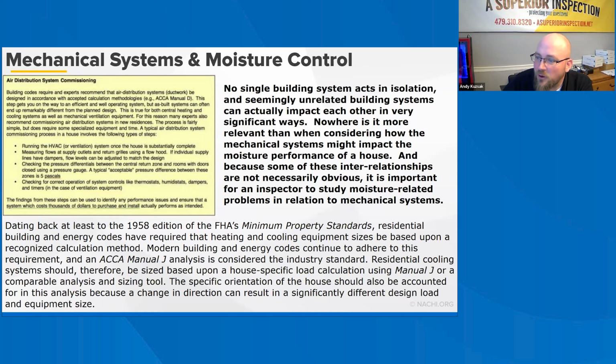It is not uncommon for a home inspector to find clothes dryers vented to an indoor or enclosed building space, such as crawl spaces. It is also common to find bathroom exhaust fans vented to the attic space or merely directed toward an attic vent. These practices are prone to create moisture vapor problems and should be avoided.